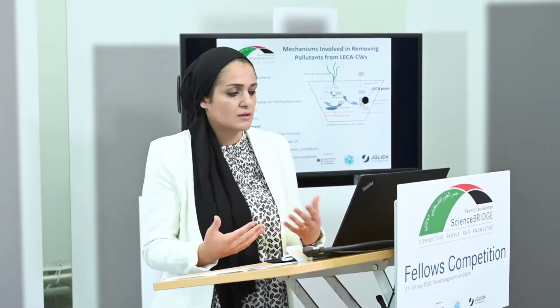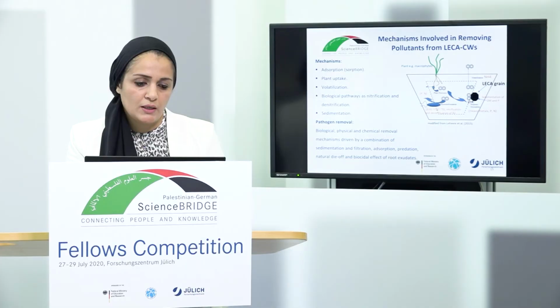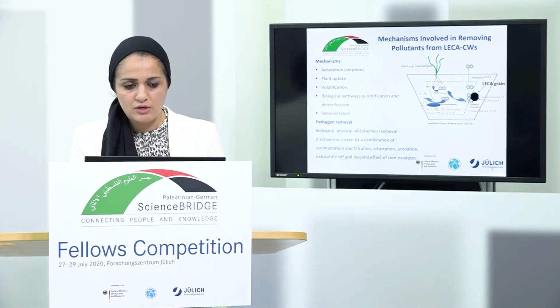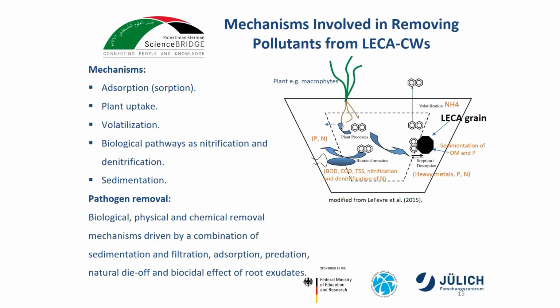For heavy metals, and also part of the phosphorus, they are sedimented on LECA surfaces. Ammonia is just volatilized in the air. Pathogen removal in LECA-based constructed wetlands also involves biological, physical, and chemical mechanisms, mainly driven by a combination of sedimentation, filtration, and natural die-off.